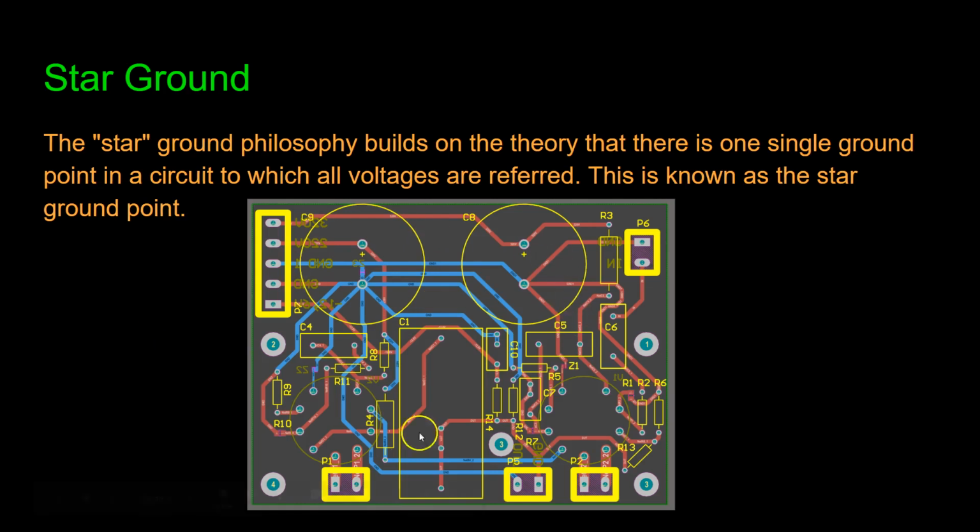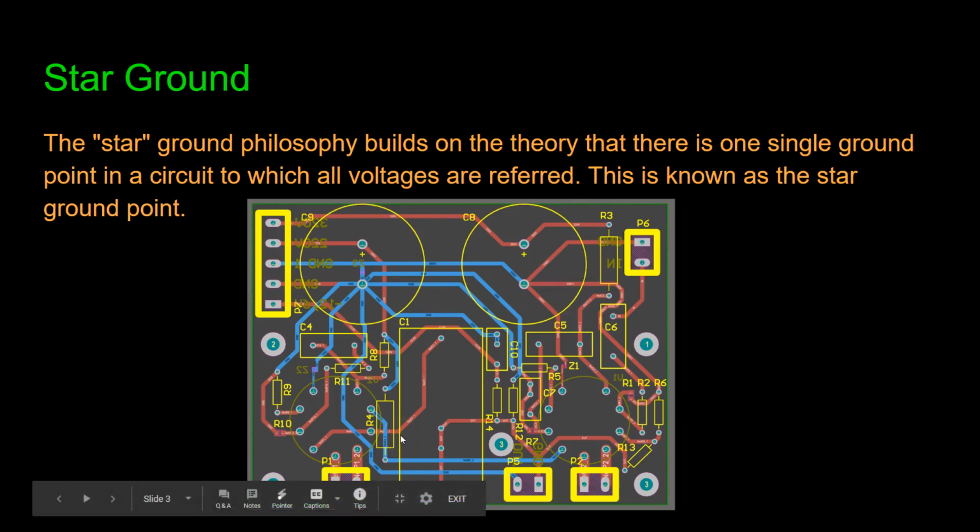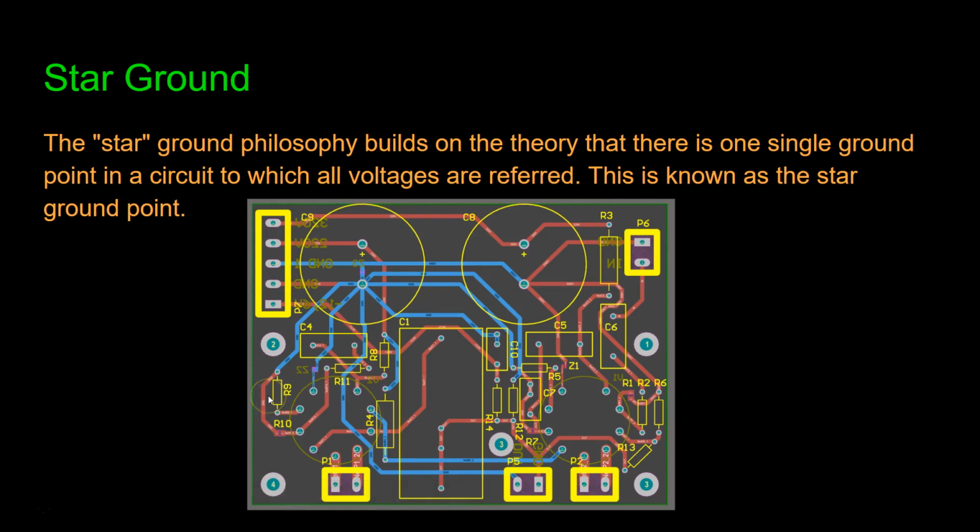As you can see in this example, it can be better understood as multiple conductors extending radially. Here you can see in blue these traces from the common schematic ground resemble a star. The important point here is that in the star ground system all voltages are measured with respect to a particular point in the ground